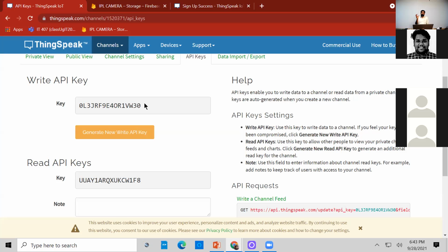Depending upon the channel A1 output, I have to control the devices connected to my channel XYZ. For that purpose, first of all, I have to read the data or the status of that sensor from channel A1 and analyze it. Depending on this analysis, I have to send some data to my cloud channel, XYZ, field 1 or field 2.